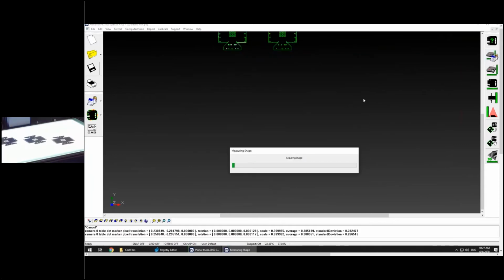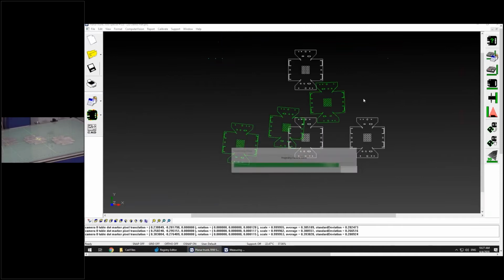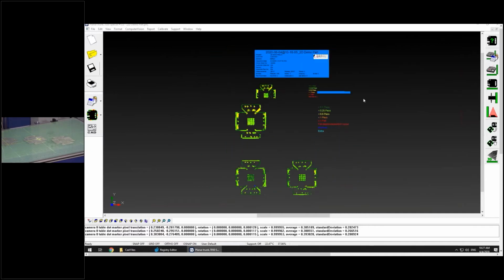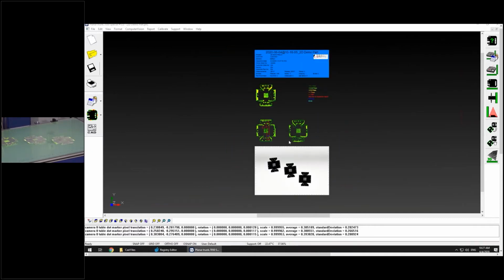So back to what I was saying, the whiskers and the blobs: I was using the blobs for operators, and whiskers are going to be more for the quality managers. The reason being is whiskers actually tell too much of the story of the part, and it gives your operators an idea of, I can see what's wrong with this part, I think I'm going to fix it for them. Well, no offense, I don't think we want that to happen, though.